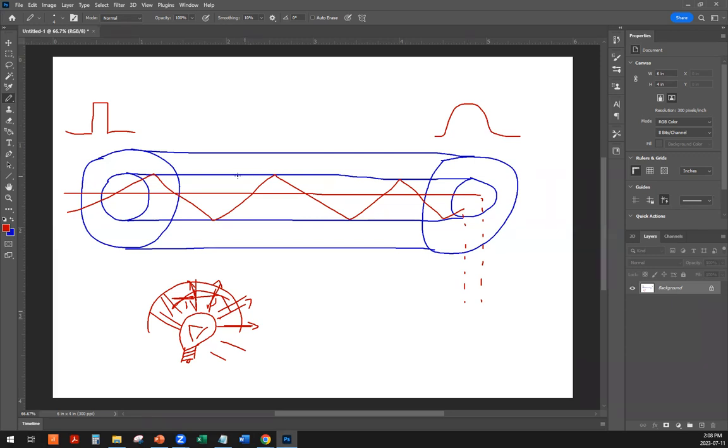All right. Now, that is because there is a difference of indexes of refraction. This is considered a step index type of fiber optic strand or conductor. We are stepping the index from one environment to another, and the step is immediate. The change is just basically from one to another environment, and it's just a dry cut kind of thing. Right?